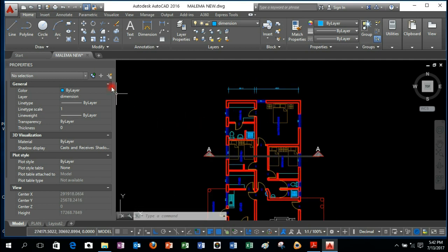So for this drawing, there is need to come up with the construction lines. The construction lines are under the draw command. So we have the draw, then you access the draw. This line is the construction line, and then we have the options here. We have vertical, angle, bisect, and offset. So it has to be vertical.